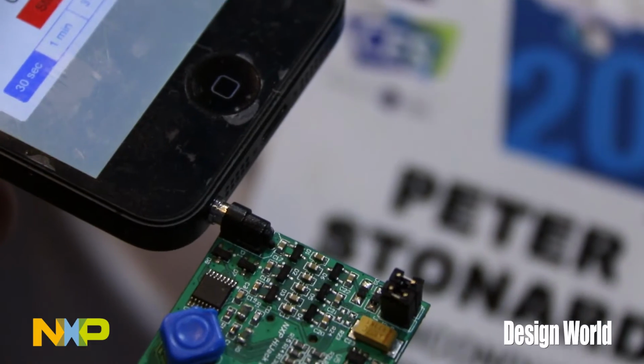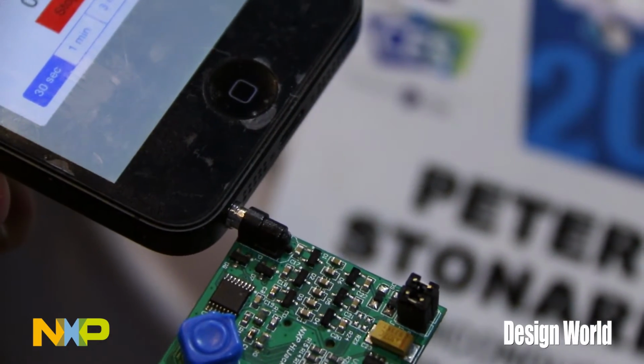That interface to the phone is quite interesting. Can you tell our viewers a little bit about how you managed to do it? It kind of looks like a sophisticated modem. Okay. It may be familiar to people who have used PayPal or Square credit card readers. These devices plug into the audio jack of the phone. The clever thing is they are such low power devices, they draw power from the audio circuit in the phone itself. One channel powers the card, the other channel communicates the data back and forwards.